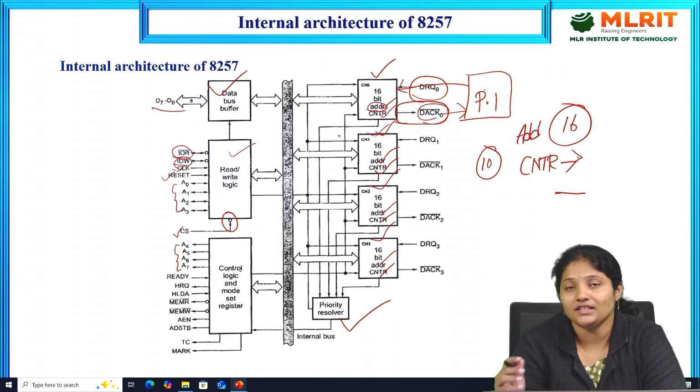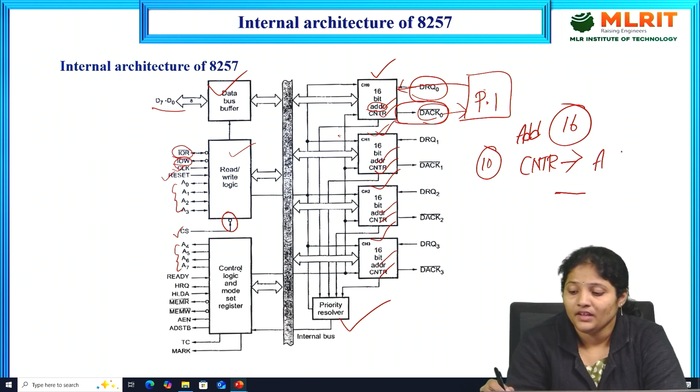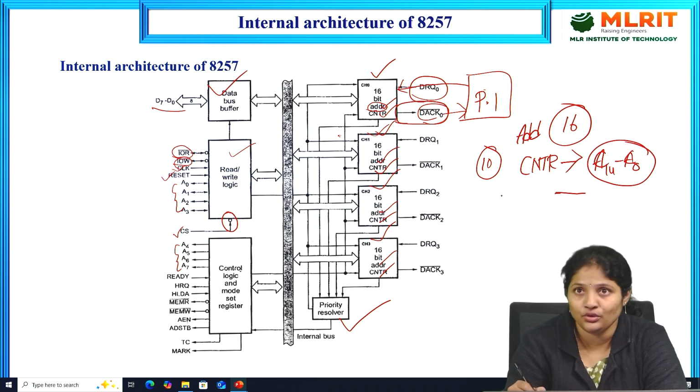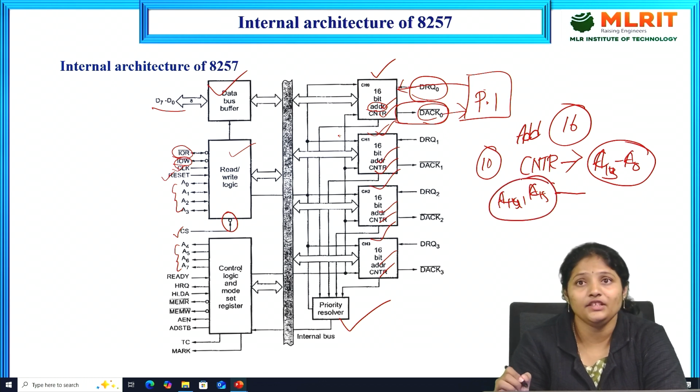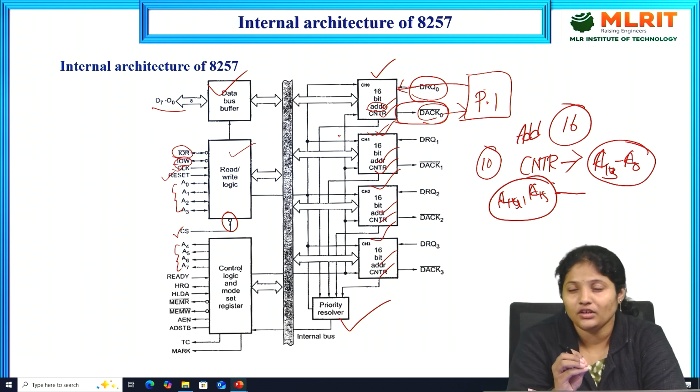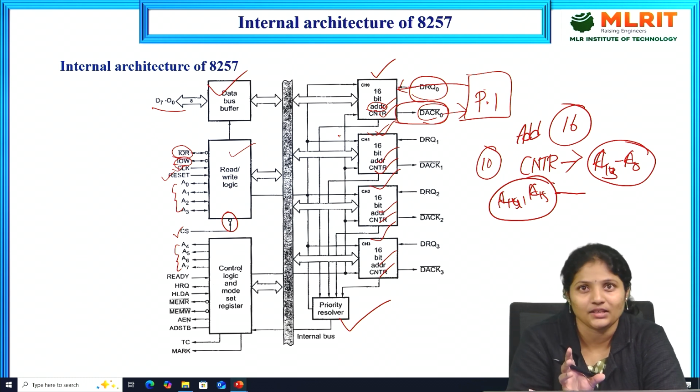That equivalent decimal number of DMA cycles should be in bits C0 to C13. So these 14 bits will be the equivalent decimal number of DMA cycles, and the other 2 bits, C14 and C15, signify whether a write operation or a read operation is being done. If each channel of the DMA controller has these two valid pieces of information, then only will the actual data be transferred or received.